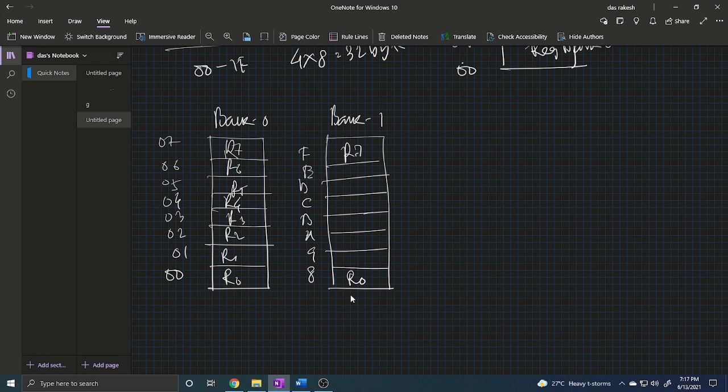So now this is the same for bank 2 and bank 3 also. Okay, so this is the process to switch the bank register from one bank to another bank using the register bits RS1 and RS0. Okay, so this is the operation of the bank register in 8051, which is very important.